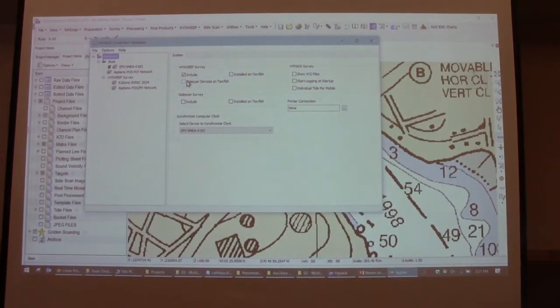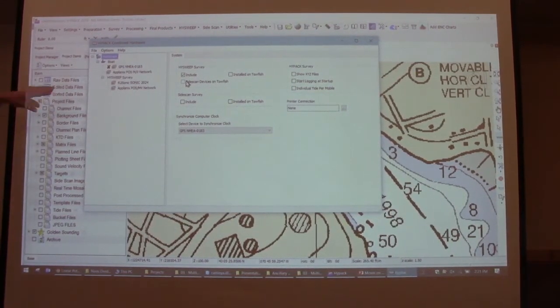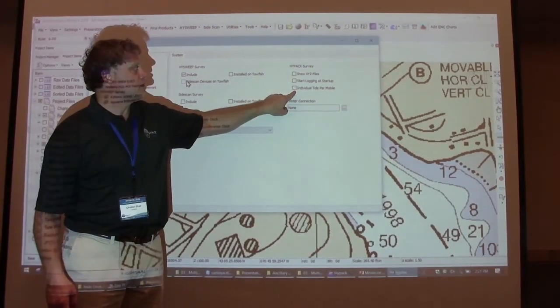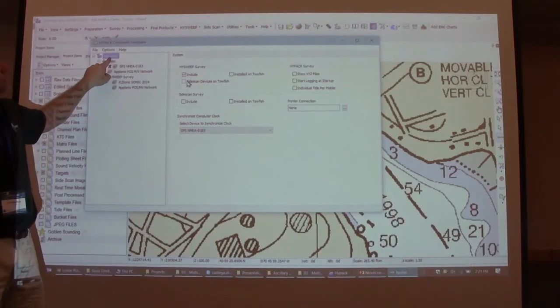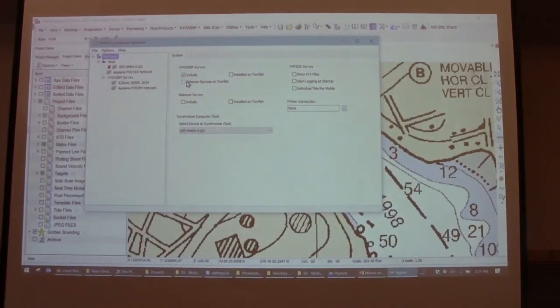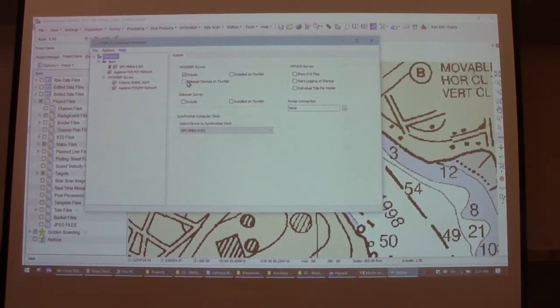You want an elevation of all 4 corners as well. And if you're going to do that, you can add 4 RTK instances of GPS DLL. And over here you have this checkbox under the hardware, individual tides per mobile. And that will compute RTK for the 4 different devices and give you 4 separate water surface elevations, or RTK antenna heights.